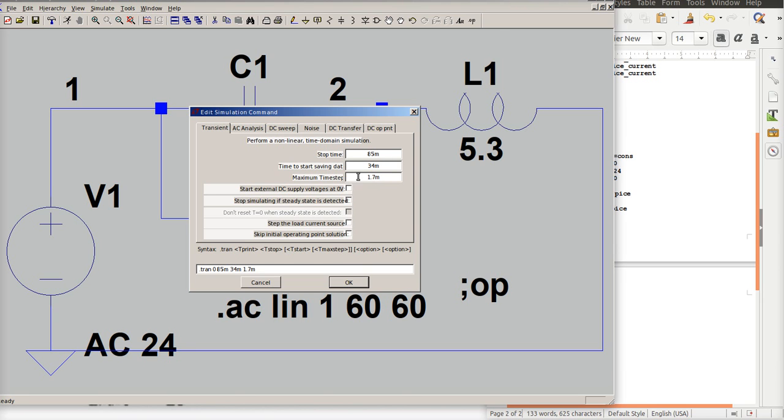The true transients that you would study, say, in an engineering school, doing DC and AC analysis: what happens when this capacitor first charges? What happens when this inductor first charges? That's what I can truly consider the transient. And then later on, after everything started up, things come to a steady state. That's no longer a transient anymore. So I'm using transient analysis, but I want to look at more of the steady state waveforms that a student would see on an oscilloscope in a lab.